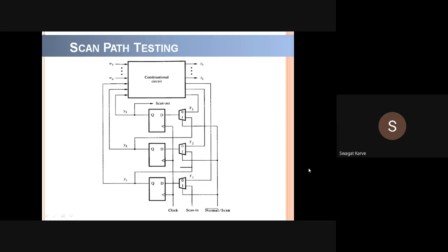That's why we have to go for different automatic and advanced testing methods, such as JTAG, scan path testing, and built-in self-test. These are the kind of automatic testing methods that can test the entire ASIC or entire chip, and that's why they are very useful. In addition, there are some prominent testing methods that I mentioned: linear feedback shift register, built-in self-test, and built-in logic block observer, right?